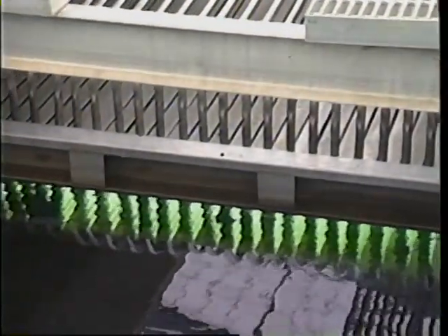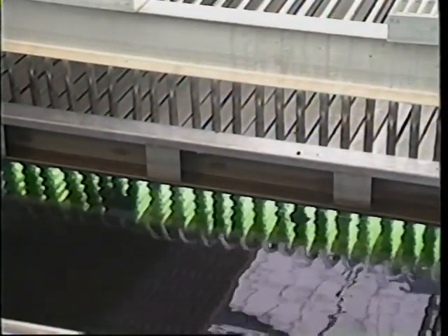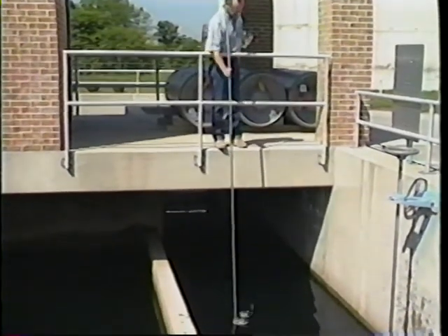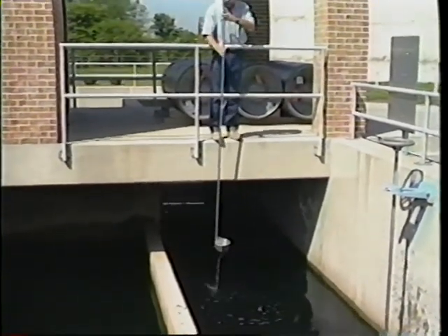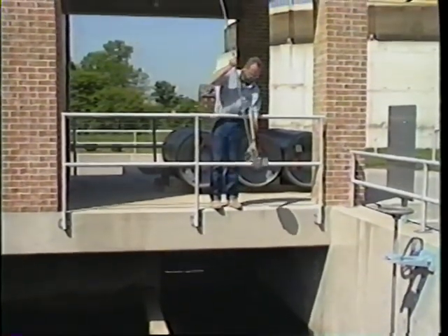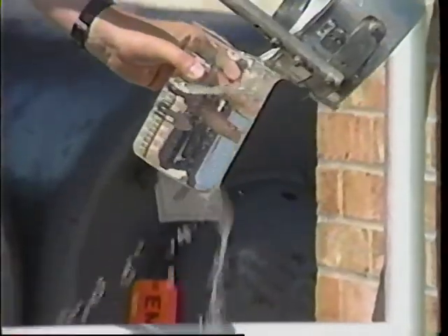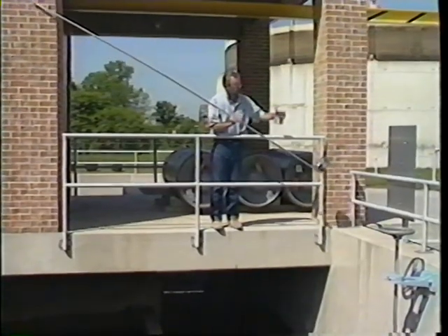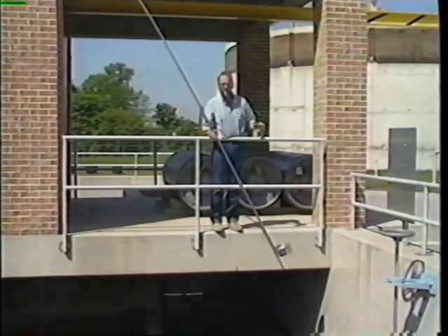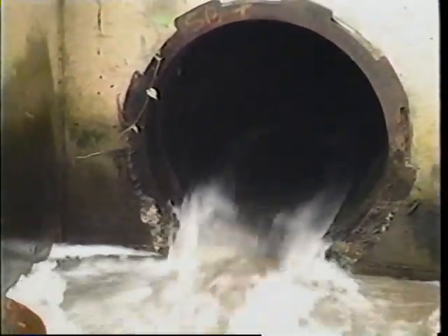Other types of disinfection processes may be used in place of chlorine. Ozone and ultraviolet light are examples of alternatives to chlorination. Proper mixing and contact time are very important and must be regularly monitored. Now, and only now, after the wastewater has been carefully processed through all treatment stages under the watchful eye of the treatment plant operator, can it be returned to the environment in full compliance with all requirements of the NPDES permit.